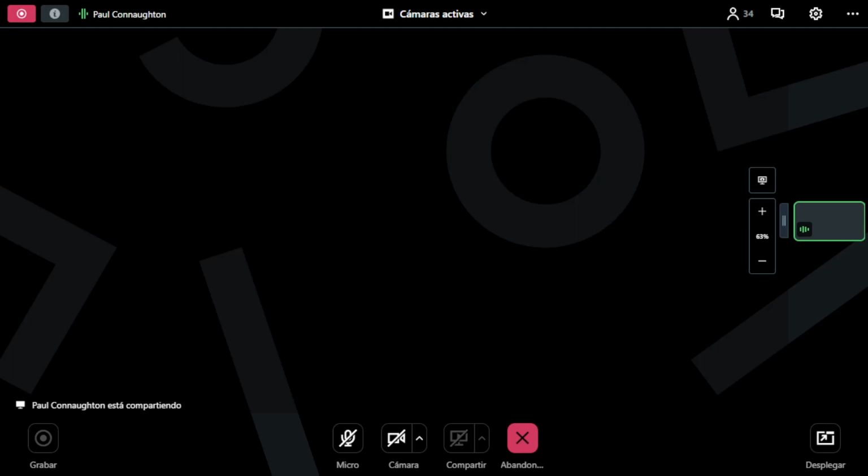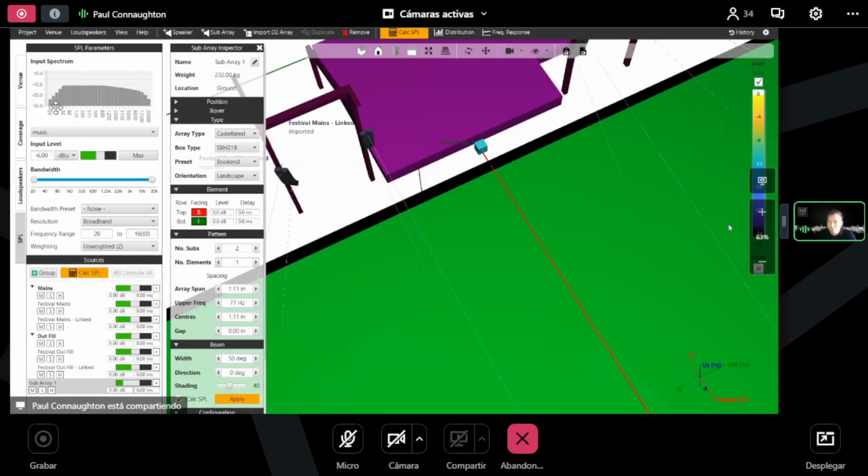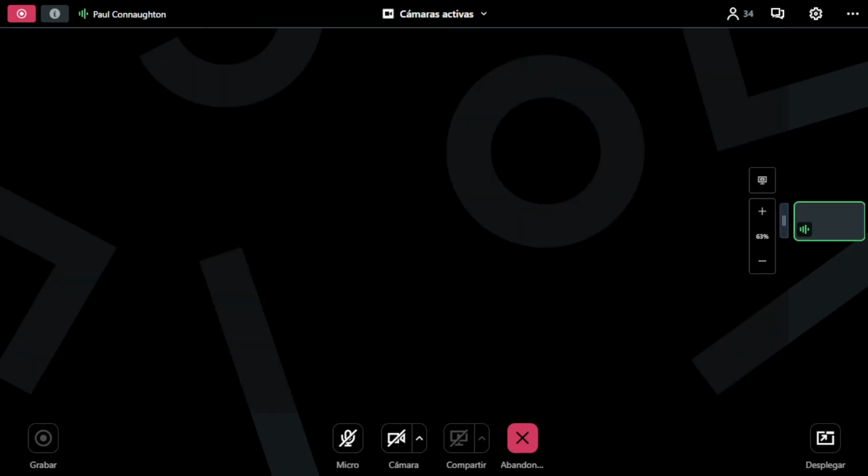Please note that in display 3, the cardioid configuration, so the time offset, the gain offset, and the polarity inversion is already included in that preset. It already knows when you are forward firing or rear firing what preset to use. So please don't add the additional time on top, because then that will obviously make everything out of time.